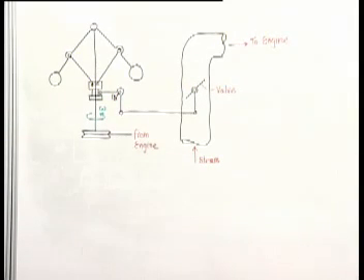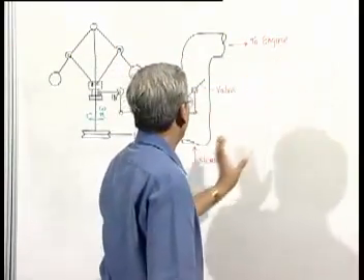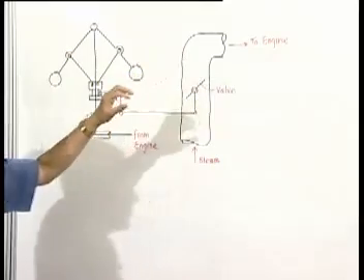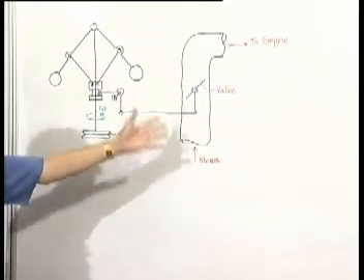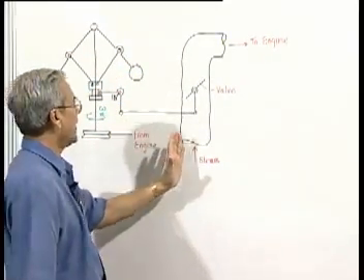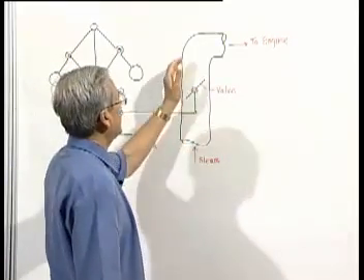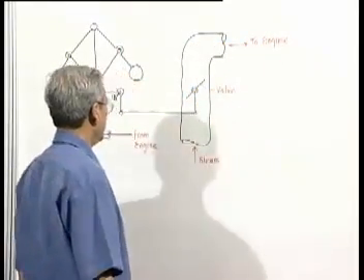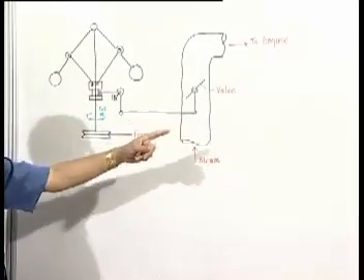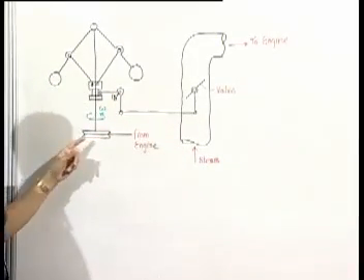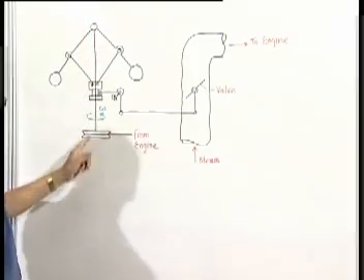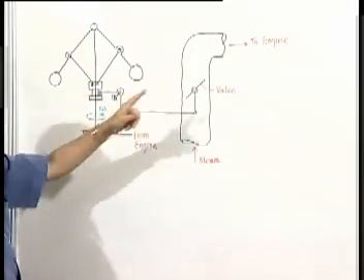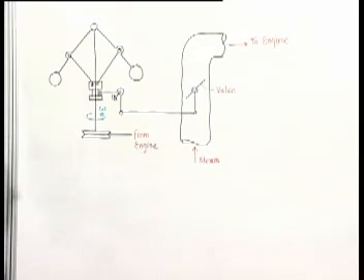Let us explain how the simplest feedback control device, first devised by James Watt, works. An engine is running somewhere, and the source of energy to any thermal engine is steam. So steam is going through this pipe, there is a valve here, and it is being supplied to the engine. When the engine is running, with the help of some kind of belt drive, another vertical shaft is being rotated, whose speed is related to the speed of the engine.